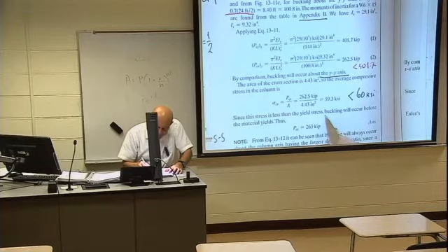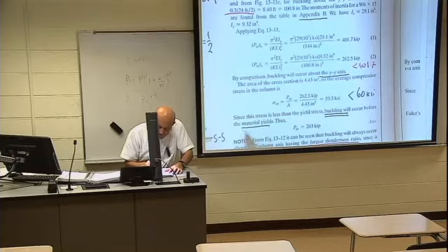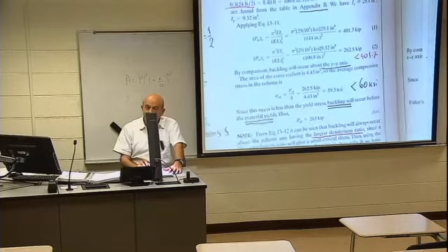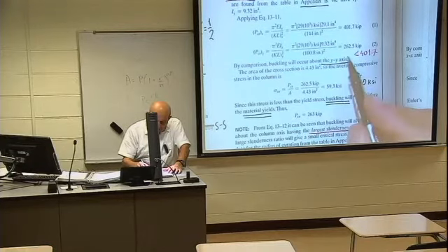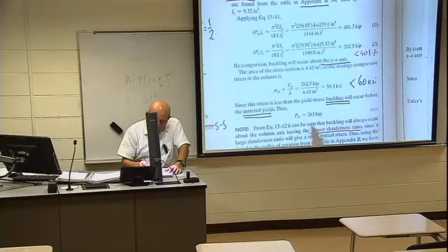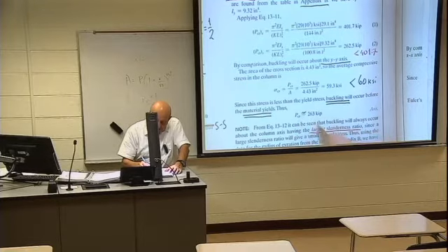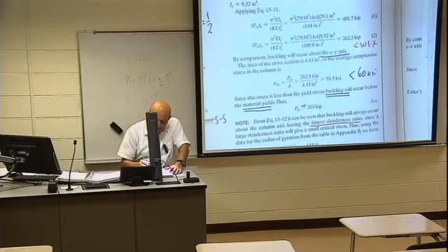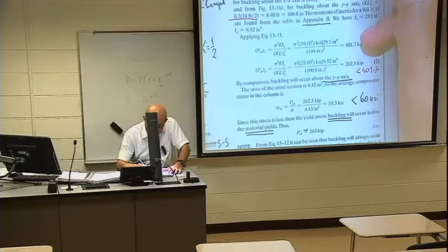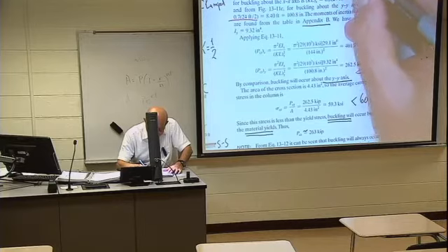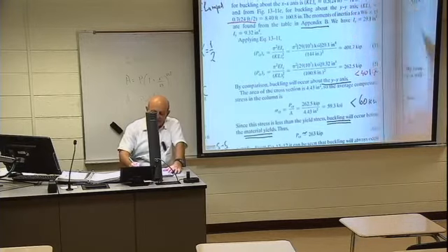So buckling is a more dangerous failure criterion than yielding. Thus the critical value equals 262.5, approximated as 263 kips. That is what we were asked: determine the load it can support. So the system can support this load.